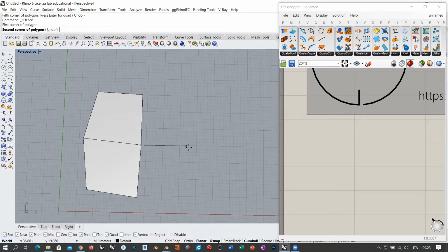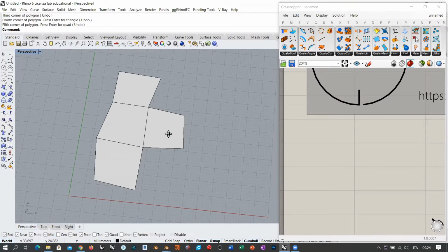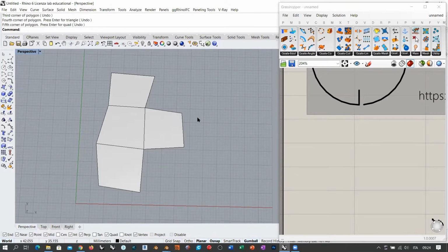You can simply pick other, I don't know, 4 here and other 4 here at the top. It doesn't matter if they're actually square. The important thing is that they have 4 corners and 4 sides, and they have 2 coincident vertices with each other. They touch along one edge. Okay. Try not to create another polygon here, for example something like this, sharing 2 edges with other polygons. This is going to create some complexity. We don't want to run into problems right now.